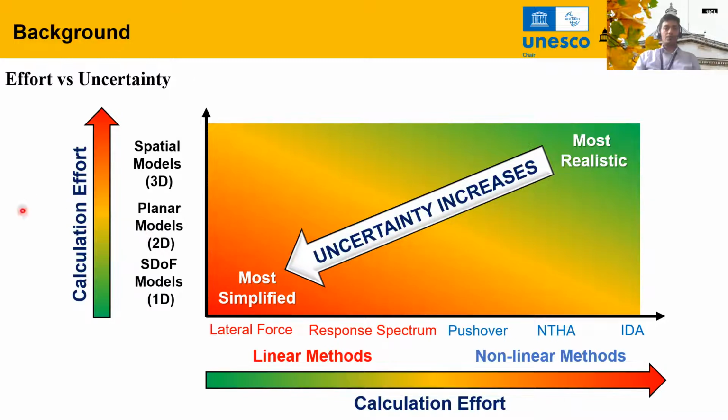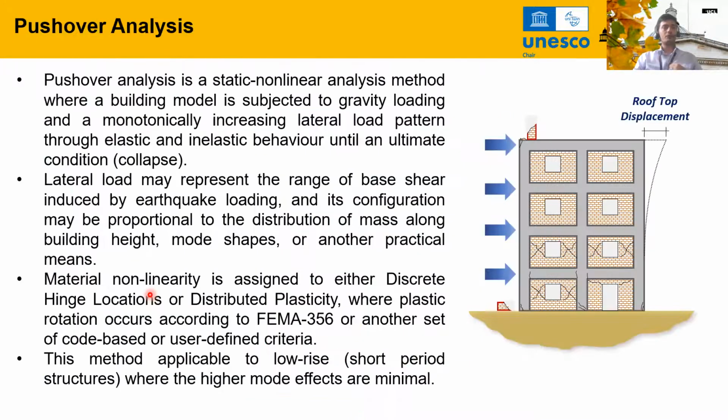For example, this slide shows the effort versus uncertainty in the results. So the computation effort increases as we go from a single degree of freedom system to a full 3D model. Similarly, the reliability in our analysis results increases from lateral force methods to nonlinear time history analysis methods. Now, as I told you already, we will focus on nonlinear pushover analysis in this session.